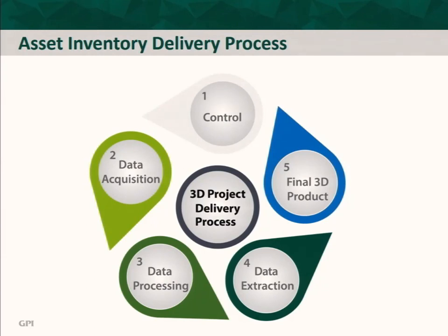So this is the cycle of any of these projects. You have to have ground control. You gotta send surveyors out in the field, set panels. You guys have seen panels on the side of the road. There could be little chevrons or a cross, and then there's a PK nail at the tip of the panel or the center of the panel. And the surveyor goes out and measures an XYZ coordinate for that panel, and that's how we georeference the LiDAR data to the control network and then tie it in so we can all be working on the same data.